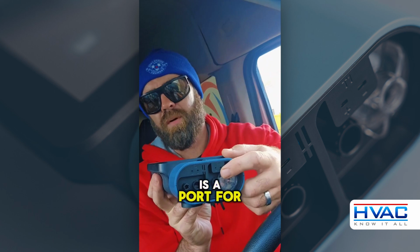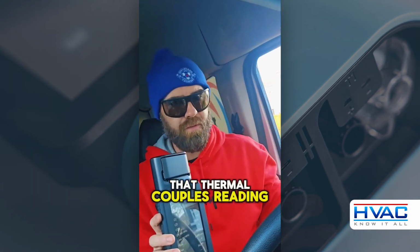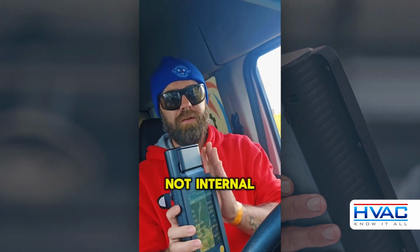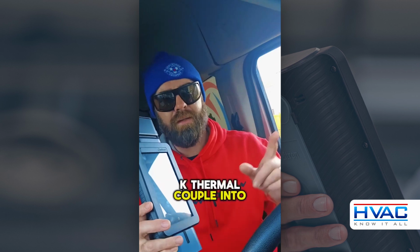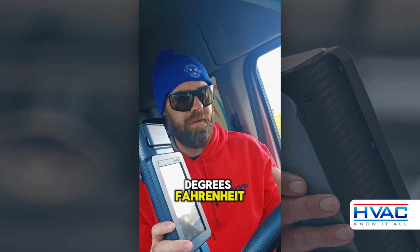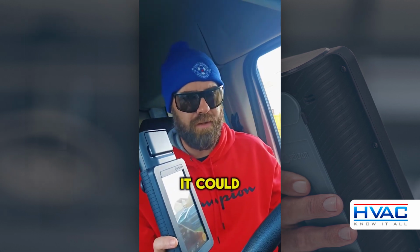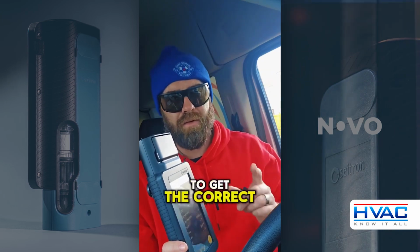What we got here is a port for a Type K thermocouple. So once you plug the thermocouple in, it's going to take that thermocouple's reading as the temperature reading, not internal to this. Essentially what you're going to do then is put your Type K thermocouple into the intake, because that intake could be anything. That could be 10 degrees Fahrenheit. It could be 20 degrees Fahrenheit. It could be all over the map. We need to know the exact temperature of the intake to get the correct efficiency.